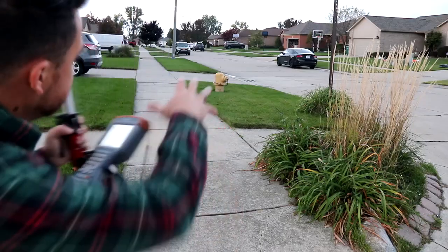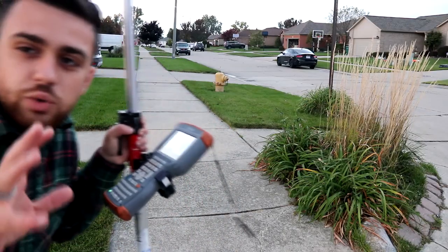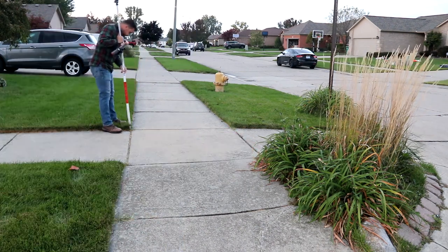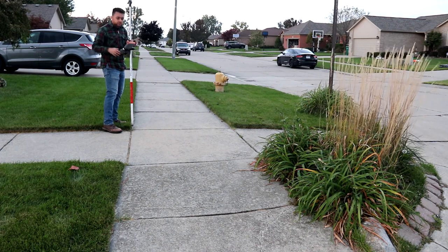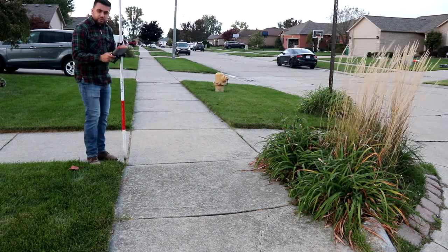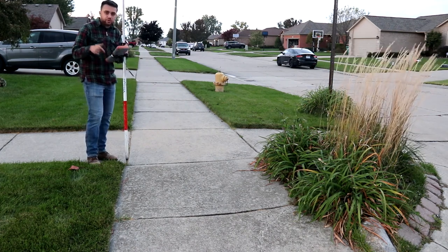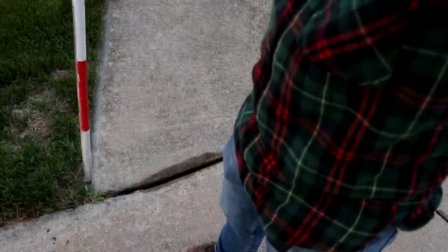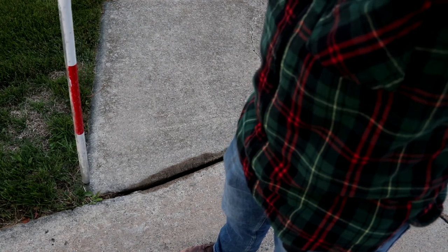Now I want to survey this little area right here. I'm going to show you how we can close out lines so that we can start to use them again. I come down to this point right here, and I can go ahead and call this concrete 1. Same thing over here, I can call this one concrete 2. However, once I come down here, you can see that the concrete actually ends right where this curb is.